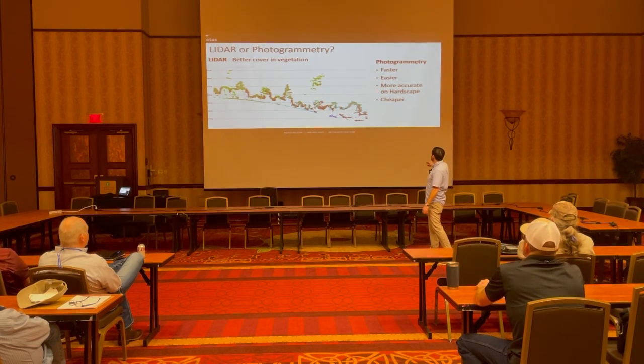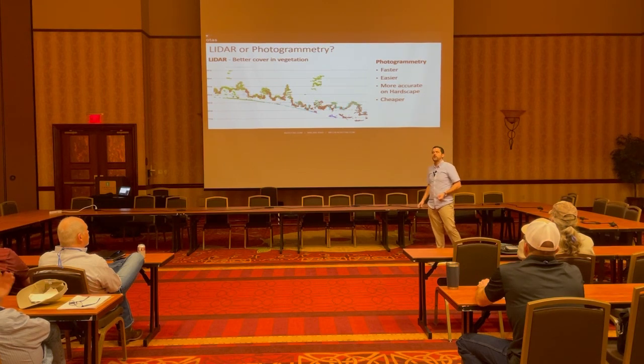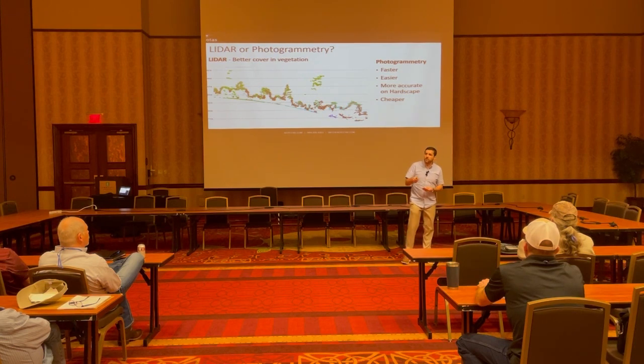But photogrammetry's benefit is it is considerably faster of a workflow, of a processing workflow overall, which I'm going to cover after the break. I'll get into the office workflow, the data processing software, all of that good stuff. It is easier. It is actually more accurate on hardscape right now. A common misconception a lot of people have is that LiDAR is going to be more accurate than photogrammetry.